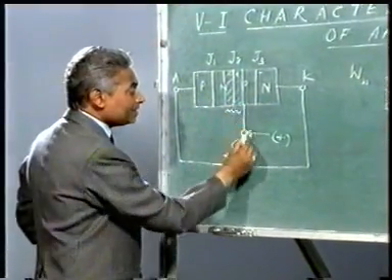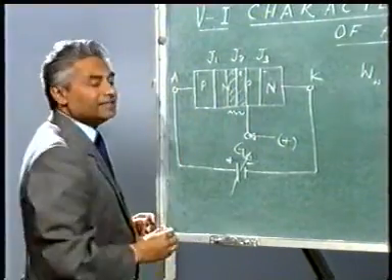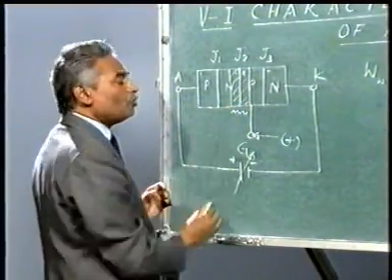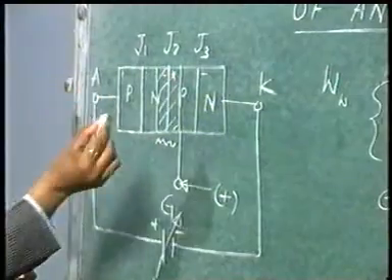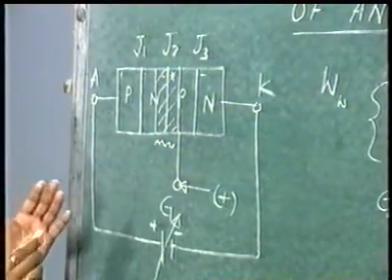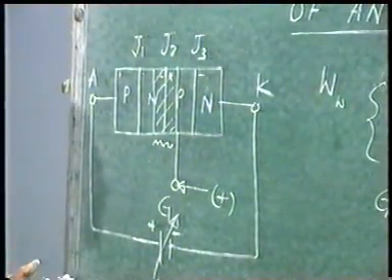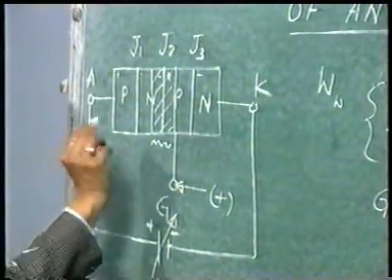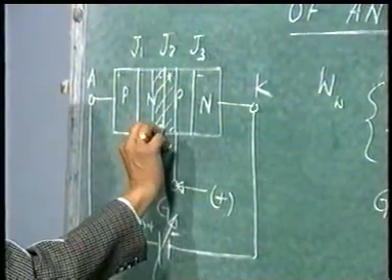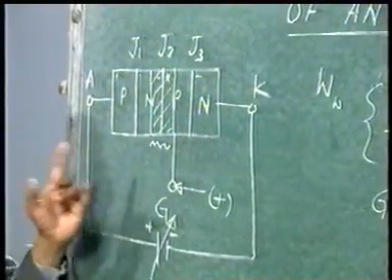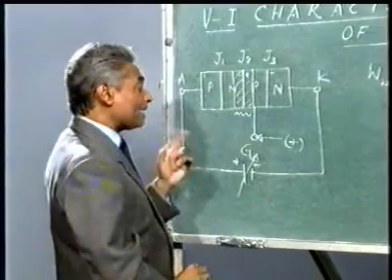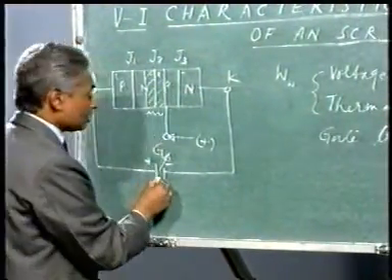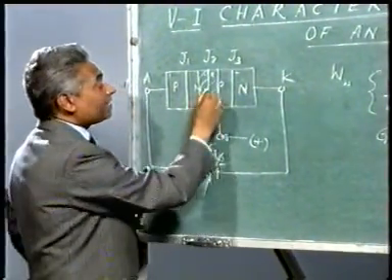You are increasing the positive charge carriers here in this layer, and with that what will happen is you are going to generate electron and positive hole pairs. That electron-hole pair generation will take place, and that will help to diffuse the current, and the current starts flowing from this junction further, and that will help conduct the device. Now what happens is that without going to such a high voltage, we can conduct the device.